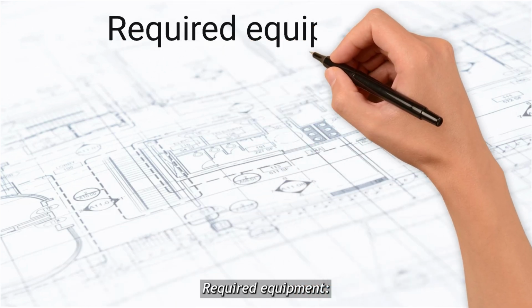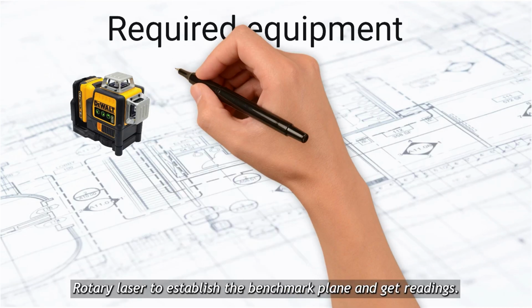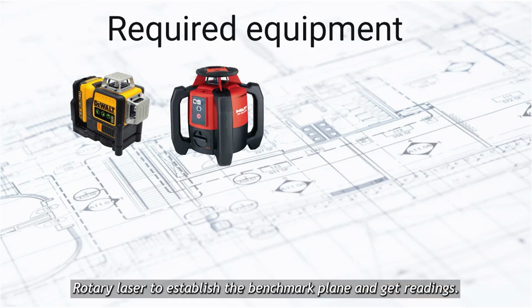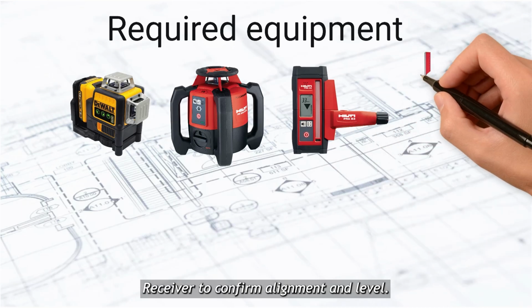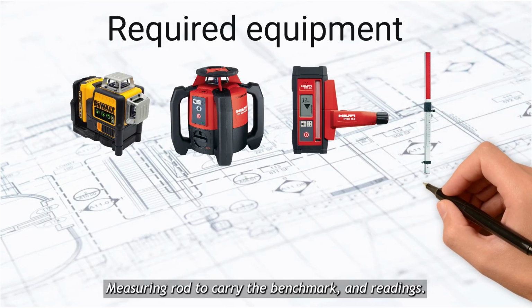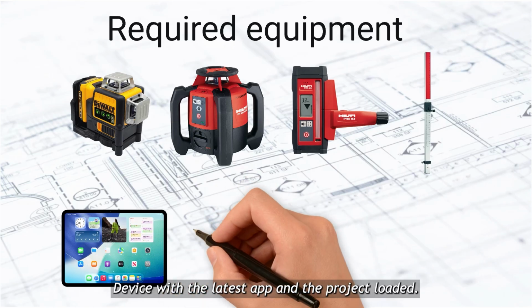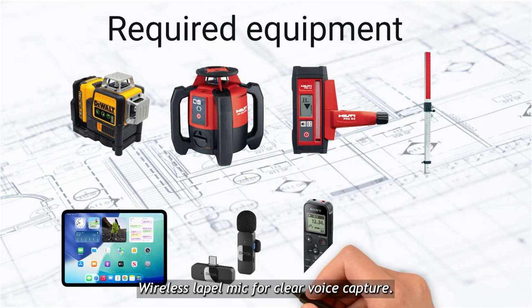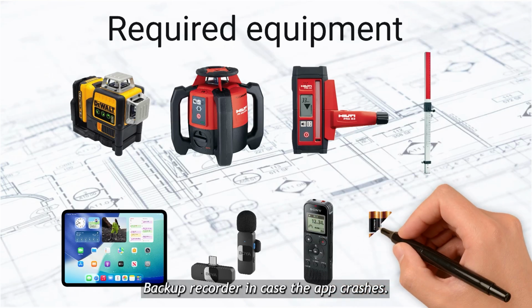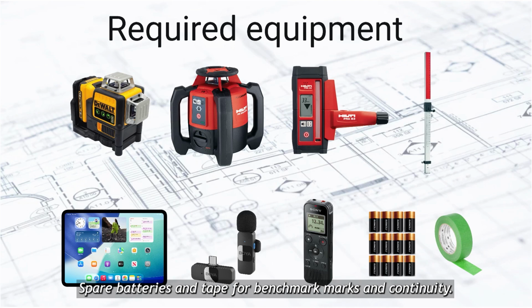Required equipment: green line laser for a visual reference line, rotary laser to establish the benchmark plane and get readings, receiver to confirm alignment and level, measuring rod to carry the benchmark and readings, device with the latest app and the project loaded, wireless lapel mic for clear voice capture, backup recorder in case the app crashes, spare batteries and tape for benchmark marks and continuity.